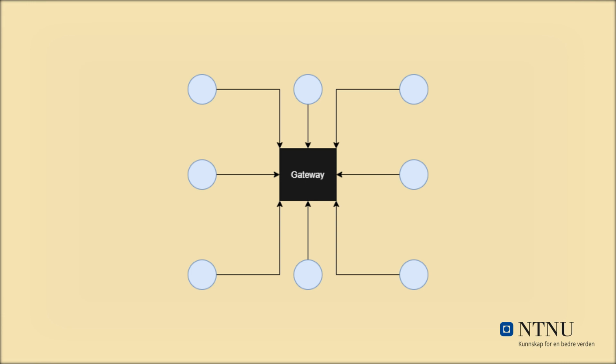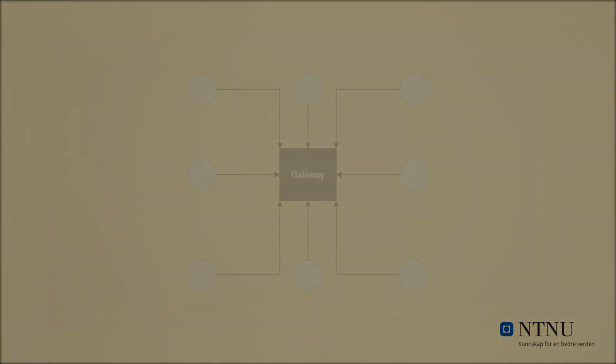Traditional wireless communications between the node and the gateway, like Wi-Fi or Bluetooth, were considered for the system, but a sub-1 GHz radio configuration was chosen as it used not only little power in transmitting, but also had good signal integrity. The system's low power consumption and good signal integrity meant that the part of the system most physically exposed would need zero maintenance for a substantial amount of time and have a robust connection to the gateway.